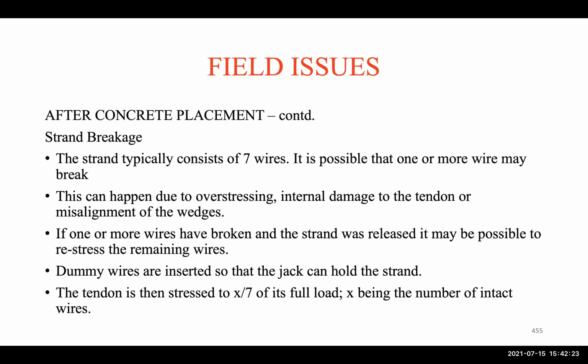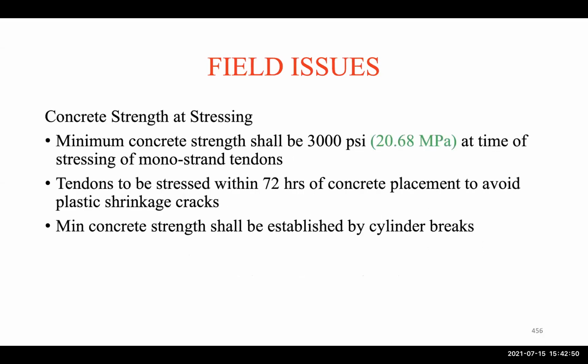Okay, and then strand breakage. So we talked about this. Either a strand is damaged or broken, then we have to apply a force. So we have 7 wires. We have to apply a force that can be taken by the 6 wires if one is broken, or by 5 wires if 2 are broken. Okay, so we have to increase the PT force.